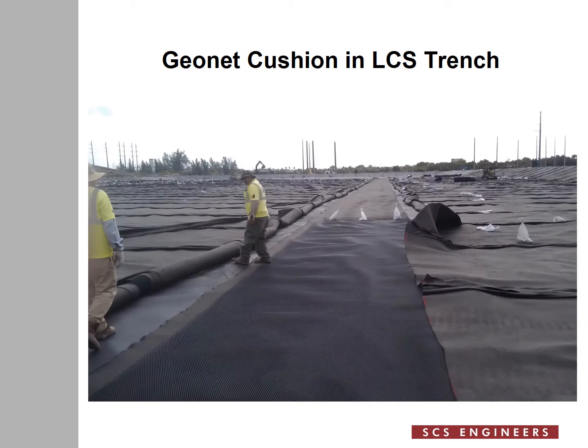After the geotextile is deployed, then geonet gets deployed. As I discussed earlier, both geonet and geotextile act as cushion in order to protect the geomembrane underneath from the gravel that goes directly on top of the geonet. Geonet prevents larger particles of gravel from reaching the geomembrane, and geotextile prevents smaller pieces that may exist in the gravel pack from reaching the geomembrane.